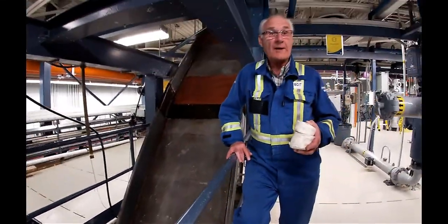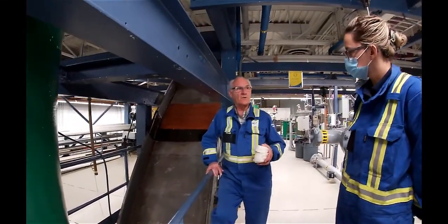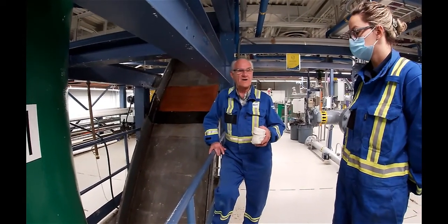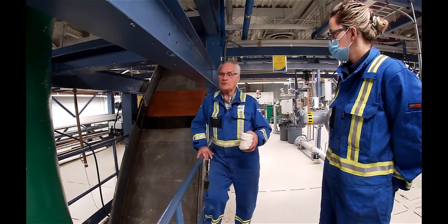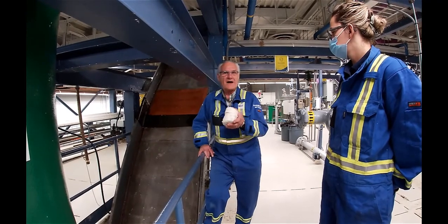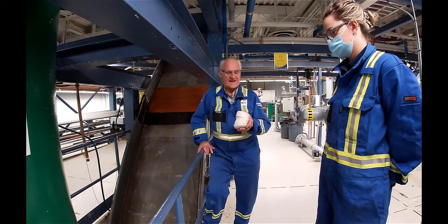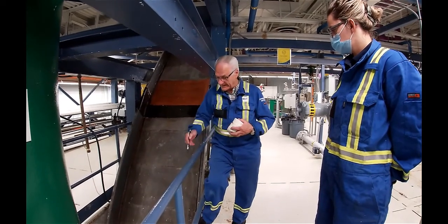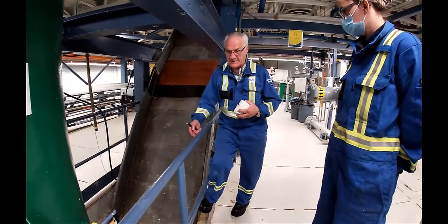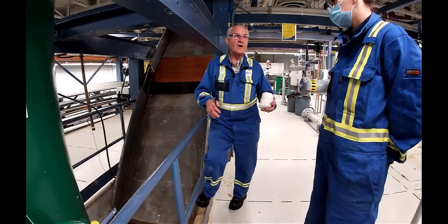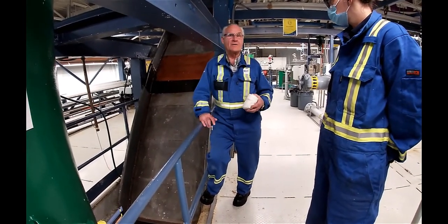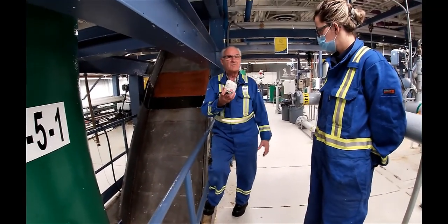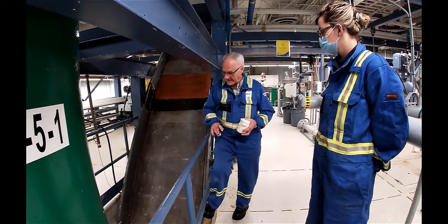They didn't shut down properly, and then it sat over the weekend and dewatered itself. Then we tried to push it out with pressure, and we compounded the problem. Eventually we had to disconnect the piece of pipe, that spool, lift it up top here and hammer it out. And these were two of the pieces that got hammered out.